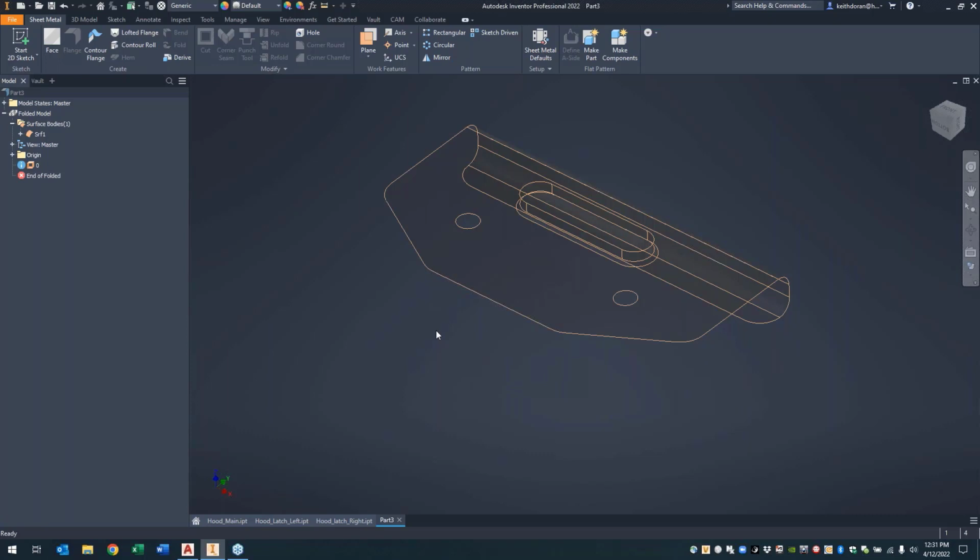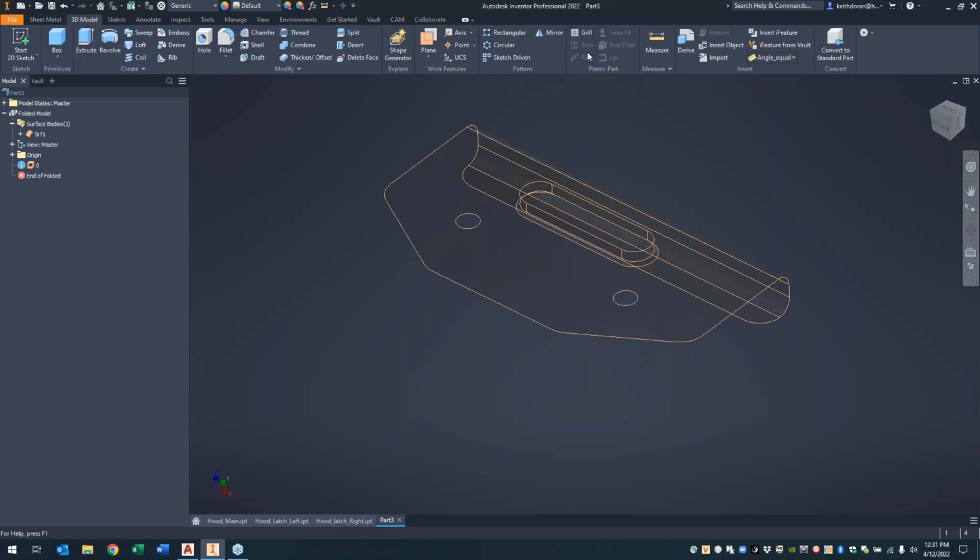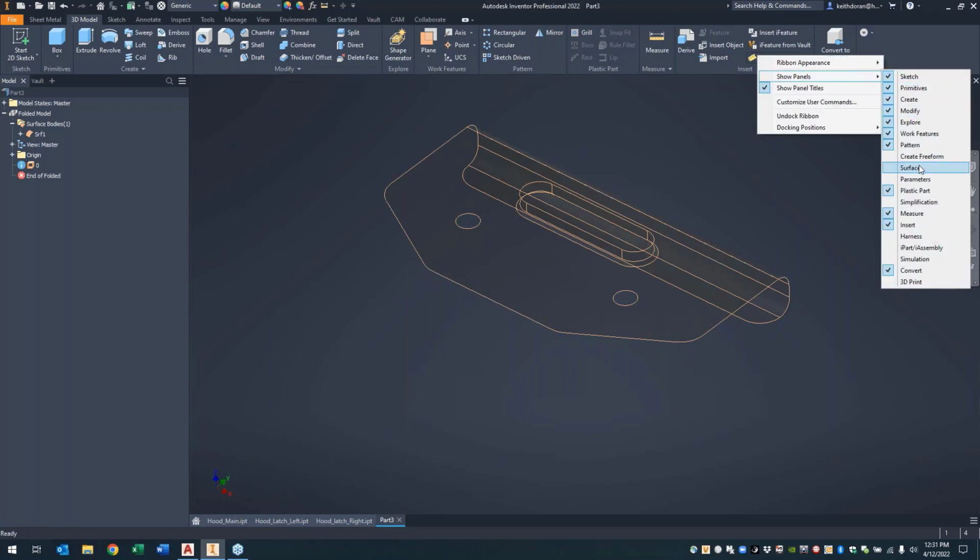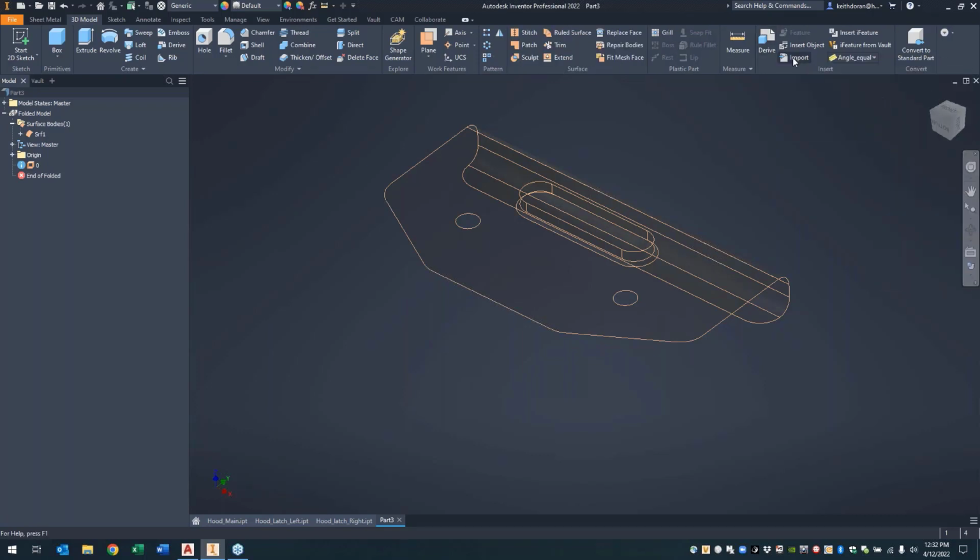However, in AutoCAD, if I didn't do that step, I would need to come in here and use some very basic editing tools on this object in order to make it function as a single entity. Right? If it was multiple surfaces, it wouldn't necessarily work for my end goal. So I need to make sure they're all stitched together. And in the 3D modeling tab, there is a stitch tool in the surfacing toolset. So there's the Stitch command right there.